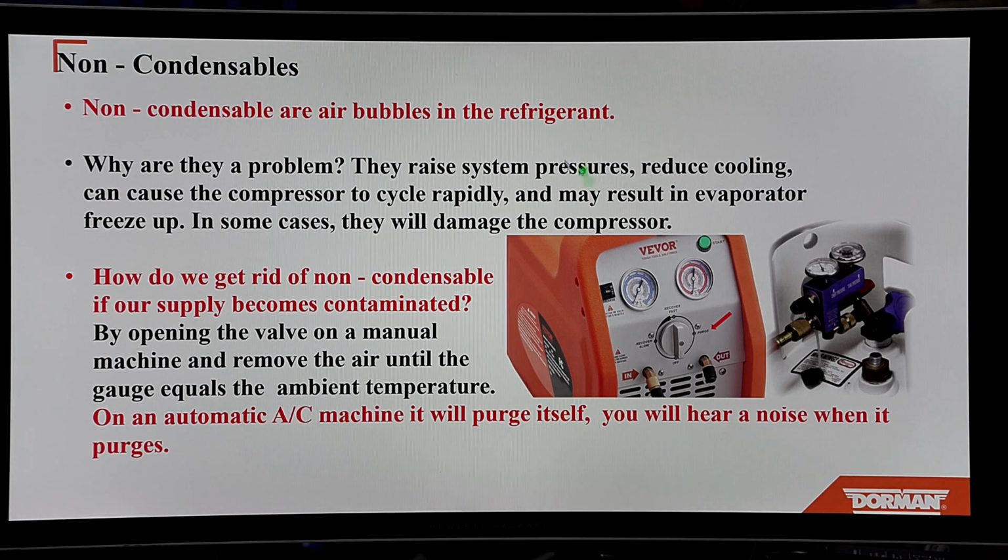Why is there a problem? It raises pressures, reduces cooling, can cause the compressor to cycle rapidly, may result in evaporator freeze up, and in some cases damage the compressor. So air is not good. Air in 134A and 1234YF causes hydrofluoric acid. That means it's going to be eating away at the components in that AC system.